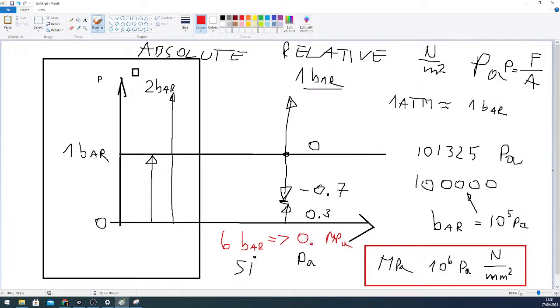Yes, we have to divide by 10 to get to the megapascal values. So that's basically usually, if we talk about calculation of the cylinders, the only conversion we have to do. We just go from bars to megapascals, and all other units will match, and the calculations will be correct in the end.